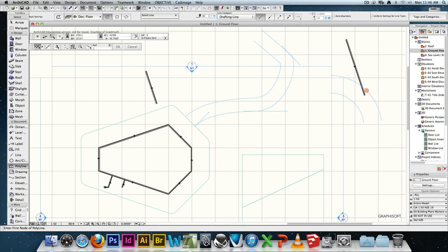Yes, I'm saying offset. So I want to draw an offset line, and I'm magic wanding the other one. No. So go to the polyline. Yeah, and you're going to use this tool here, which is the offset. That one, yeah. And you're saying follow that line, so you hold the magic wand down. Just click, and then click on that curve. You can let go of the space bar now. You see? So what you're saying is, I want to draw this shape, but offset.